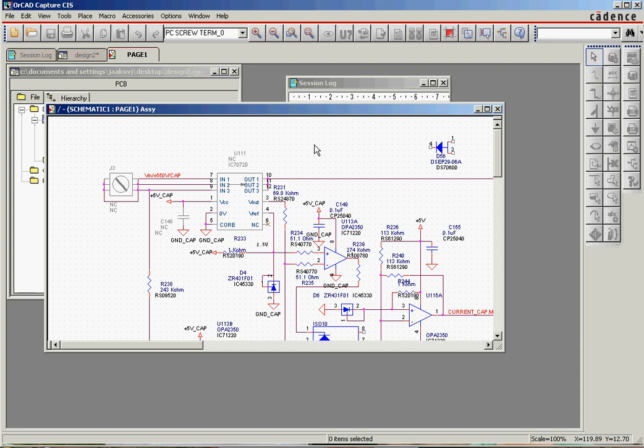The part manager is closed because we do not have the ability to change anything in there. As you can see, the components that are not connected have changed color, and the value, the text info, has been changed to NC as set in the DBC connection file. When we are in variant view mode, we cannot move any component, we cannot do anything in the design. It is locked for editing.